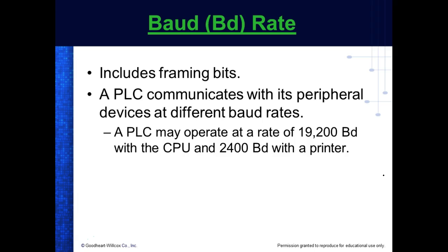If I could ride 4 binary digits on each carrier, that would give me 16 combinations. So that would be 9,600 times 16. That's how fast you would be sending the bits.